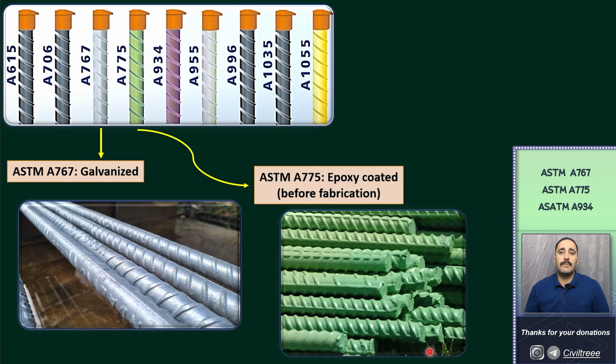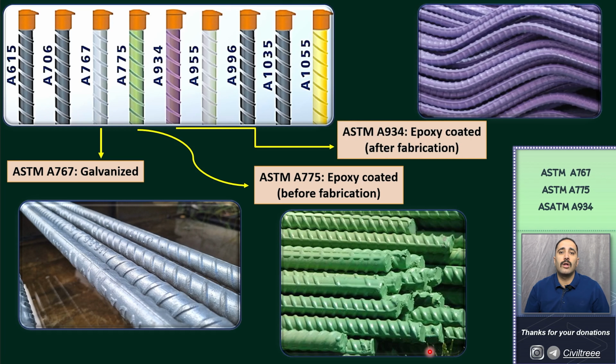ASTM A775 reinforcing steel has an epoxy coating that protects the bar from corrosion. The coating, which is typically green, is applied before fabrication, similar to ASTM A767 reinforcing bars. Epoxy-coated bars are used in environments where corrosion may be an issue. Note that chips in the epoxy can lead to concentrated corrosion, so care needs to be taken when handling epoxy-coated bars. Similar to ASTM A775 reinforcing steel, ASTM A934 reinforcing steel is also epoxy coated. The coating for ASTM A934, which is applied after fabrication, is typically purple or gray.